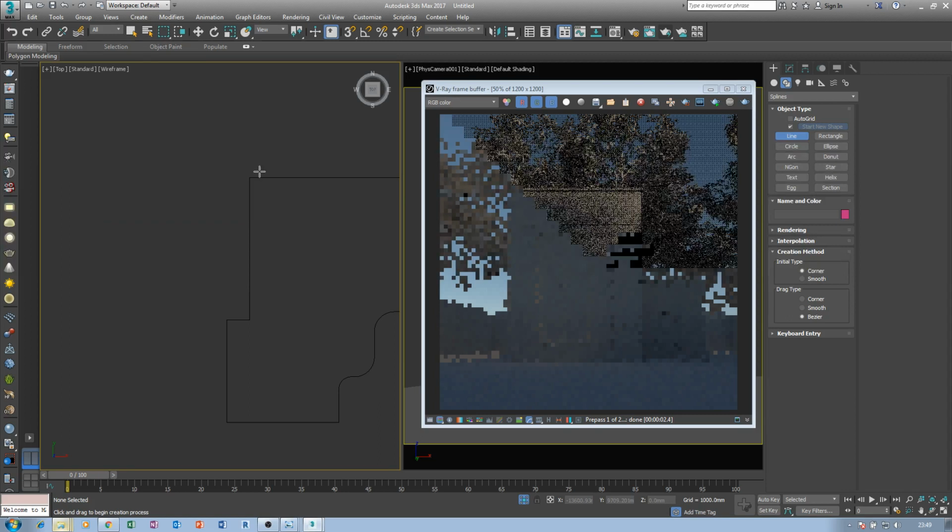If you like, you can press S to use snap, but I don't like using snap, so I'll just press shift for a straight line, shift again. You can see there is a Bezier corner, but it's not a problem. I'll see how I can handle that one later.